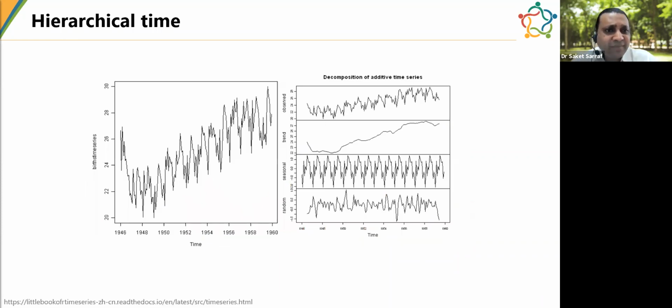Another way to look at hierarchical time is, suppose this is 8760, then you decompose it in a manner that gives you the annual trend, or trend across the months, right? And then from that you distill what the cycles are. The trend can be of different months, and then the cycles can be weekly cycles, right? And the sub-cycle can be, in each week, a cycle of different days, and then there'll be some random component because the weather itself has randomness, right? So you look at the whole annual thing and then decompose it into smaller parts, and you're constantly saying, this is what is happening at the weekly level, this is what is happening at the monthly level, and this is what is happening at the hourly level, right? And this helps you to understand how your building is reacting to different weather elements and occupants.